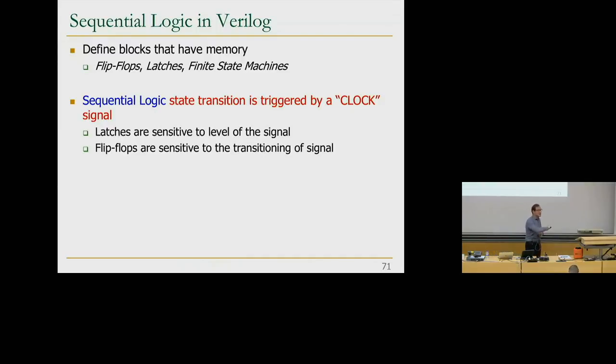But in Verilog, you can describe state transitions on any signal, as we will see. You will do a lot of synchronous design going forward, so I would suggest using just the clock to trigger state transitions in finite state machines. Some things that I'm going to describe over here will be asynchronous, in the sense that some of the state transitions will happen maybe with some other input changes, not necessarily clock changes. Right? That's a very different design. It's asynchronous design. That's not what we're going to do in the labs, but sometimes it could have its use also, because clock has some overhead, as we will see tomorrow. If you do asynchronous design, you can get rid of that overhead. But you will see this tomorrow because there's some overhead in terms of communicating the clock. Okay, so basically, we're going to trigger state transitions. Remember, the latches are sensitive to the level of the signal.